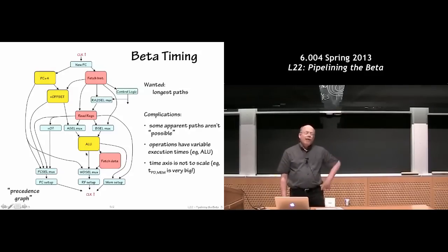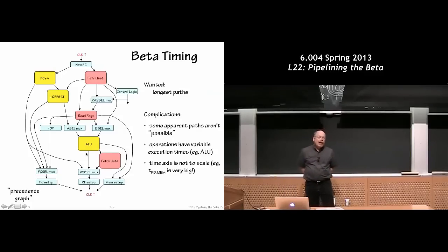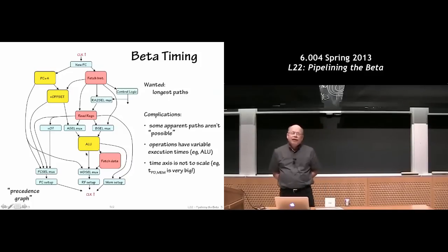And those ripple carry adders are actually slow, and some of the design project handouts talk a little bit about how other adder architectures are probably 3, 4, 5 times faster in terms of the actual nanoseconds it takes to do a 32-bit addition than the simple adder architecture that we use. But nonetheless, in the timing diagram, we have to look at this and say, well, the ALU is sort of in the way here.